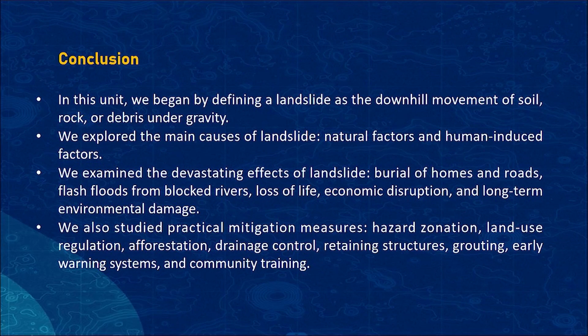We also studied practical mitigation measures such as hazard zonation, land use regulations, afforestation, drainage control, retaining structures, grouting, early warning systems, and community training.